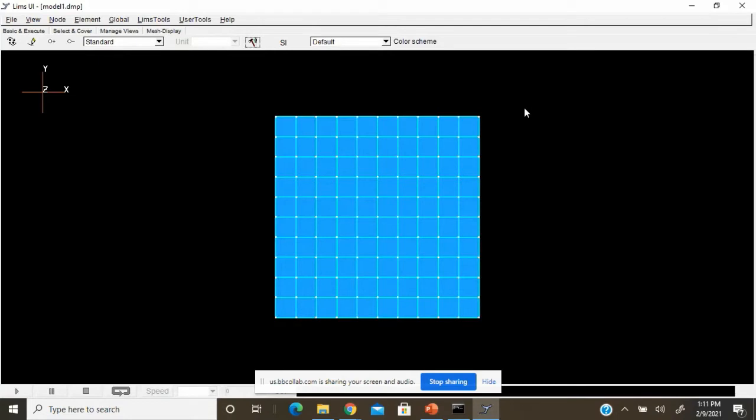Once we give the input condition, we have to define how the elements are, meaning to say what the properties of these elements are. In other words, defining the volume fraction as well as defining the permeability. Once we do both of these, we can then move on to the third step. The third step is where we set the properties of the resin itself. So the resin property, viscosity, is what we are going to set. So let's move on to the first step.